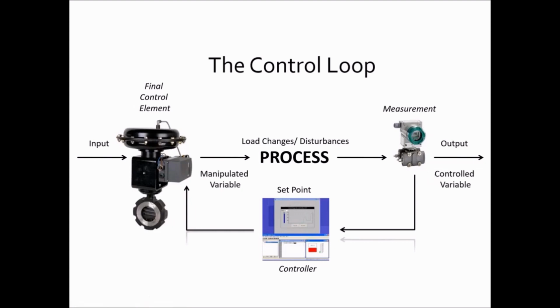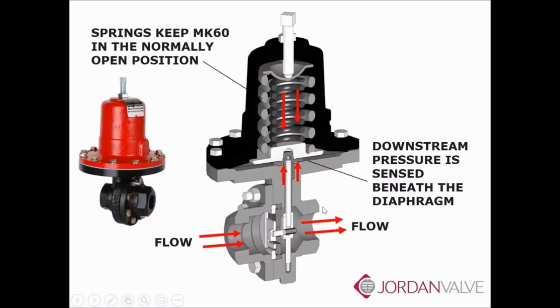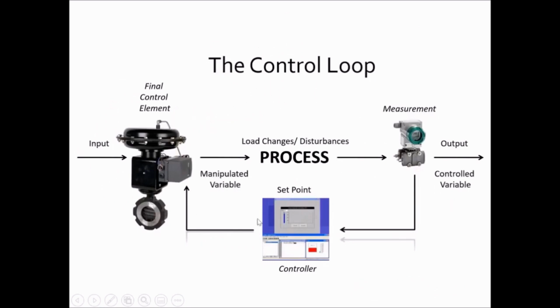So control valves are extremely accurate. Regulators, lesser so, but there's obviously a cost difference between a regulator, one piece of equipment, and control valves, PLCs, pressure transmitters, and everything that goes in between. If feedback is needed, if it's a critical process, control valves may be desired. For some applications, if we're just taking 100 psi of nitrogen and want to regulate it to 30 psi, regulators may be more economical, an advantage there.